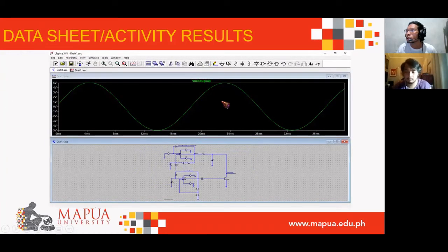You can see in the figure the sinusoidal modulating signal, which is generated by the WBO or Wien bridge oscillator. It has a 52.9 hertz oscillation frequency, where the frequency of oscillation can be computed using the formula f equals 1 over 2 times pi times RC, where we use the two RC networks or the feedback networks.